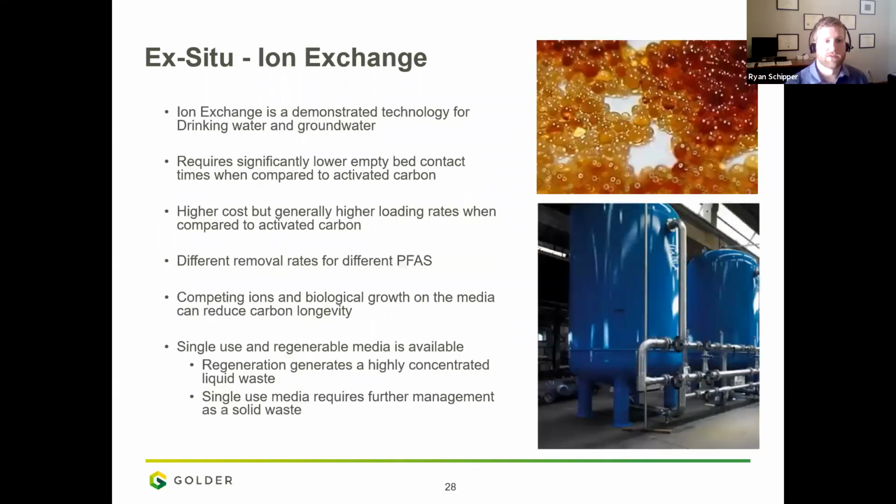One of the other probably most demonstrated technologies for drinking water and groundwater is ion exchange. This requires a significantly lower empty bed contact time when compared to activated carbon. That means we can have vastly smaller columns, reducing capital cost.